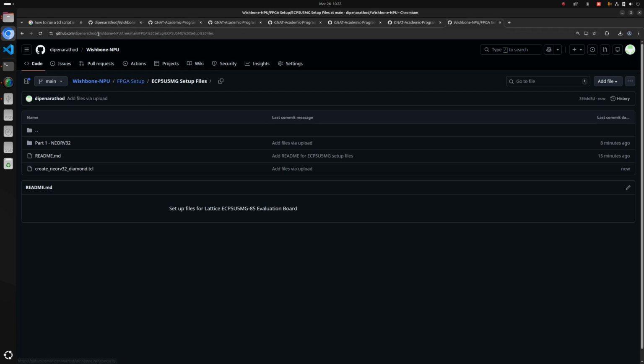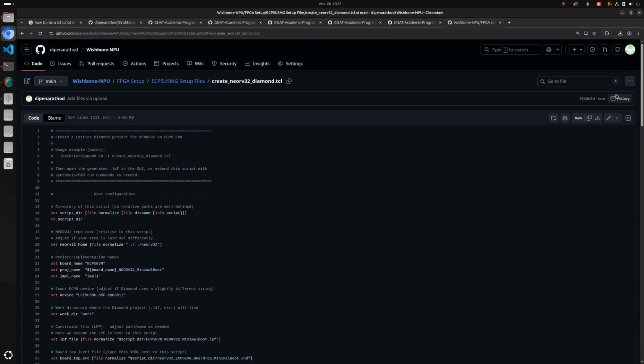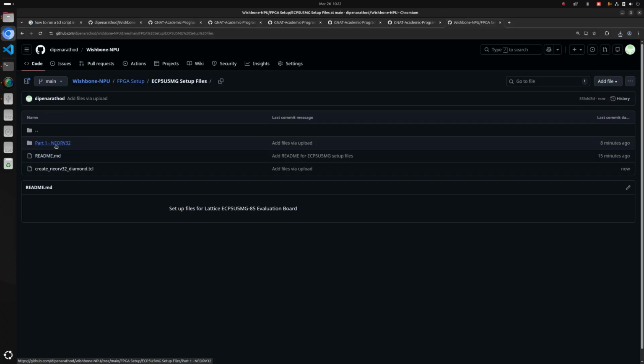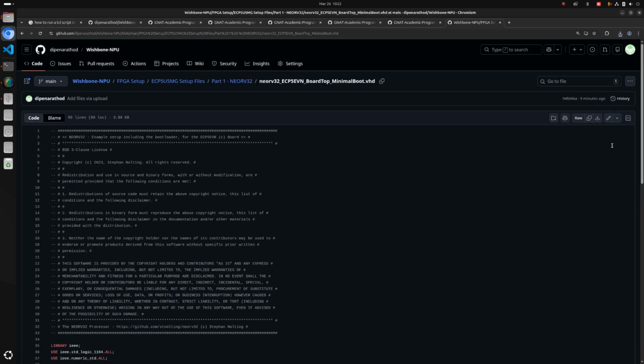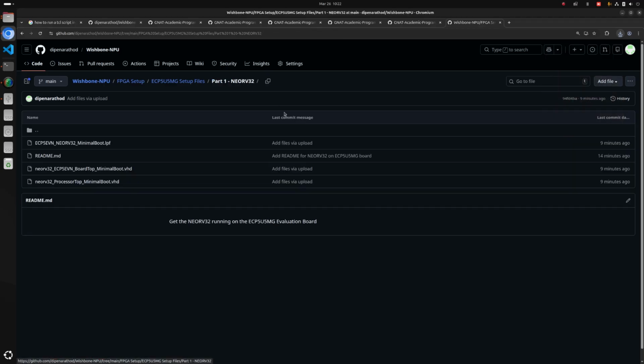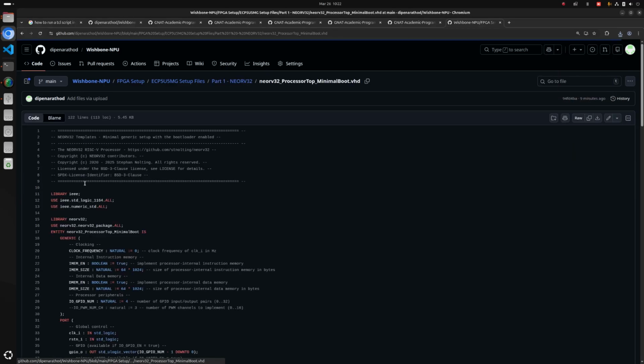So firstly, go to this repo, again linked in the description, and here get the Diamond TCL file. Let's download it. We'll use the part 1 files for this video. So we'll need the constraints file, the NEORV32 template file, and the ECP5 minimal main top level. So this will be our actual top level file. Download the top level file first, and also we'll download this only.